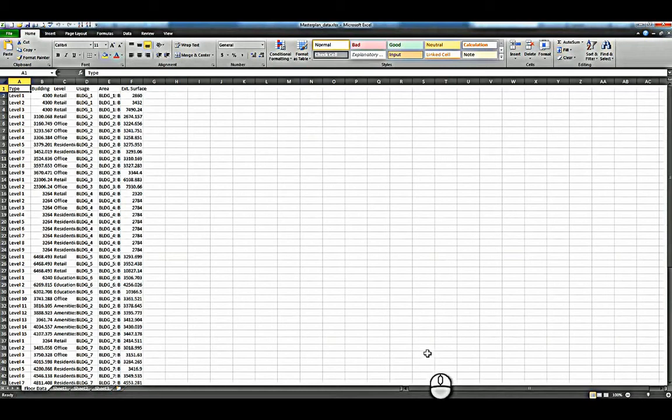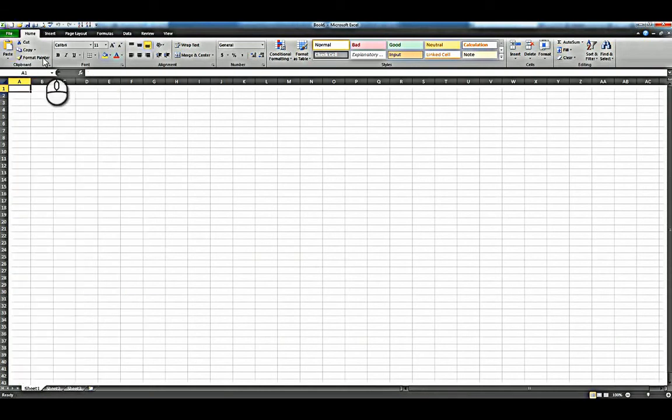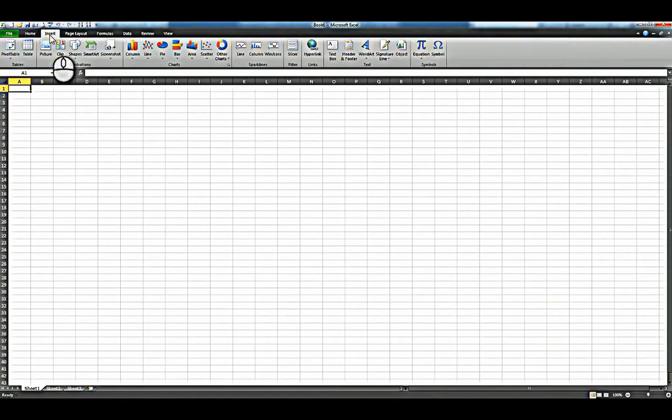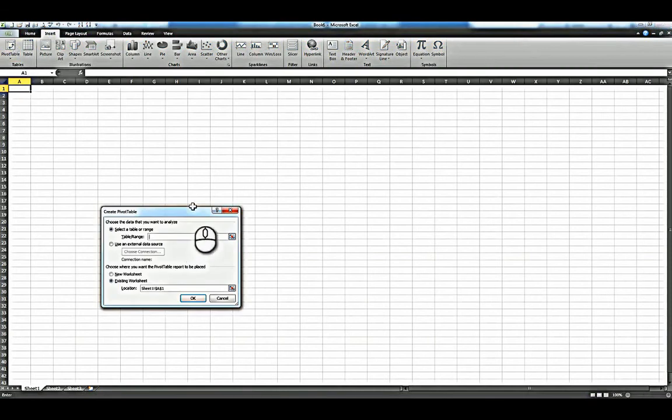The pivot tables can pull the data from multiple data stream connections, if you will. If you keep that dashboard as a separate file, you can reuse it for other types of data from other Dynamo scripts that you've created or other Revit projects that you're working with. So I'm going to create a brand new Excel file, and then we'll head over to the Insert tab. In the Insert tab, there is the Tables panel and the Pivot Table command. I'll start that command.